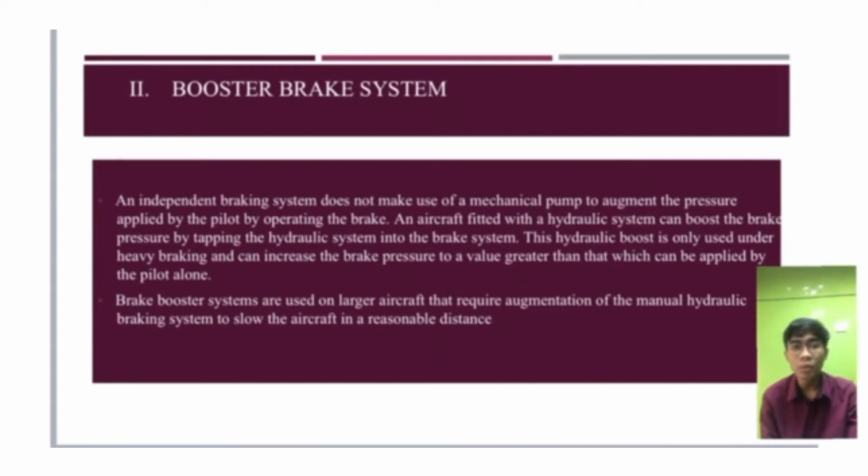The hydraulic boost is only used under heavy braking and can increase the brake pressure to a value greater than that which can be applied by the pilot alone. The brake system is used on larger aircraft that require augmentation of the manual hydraulic braking system to slow the aircraft in a reasonable time.